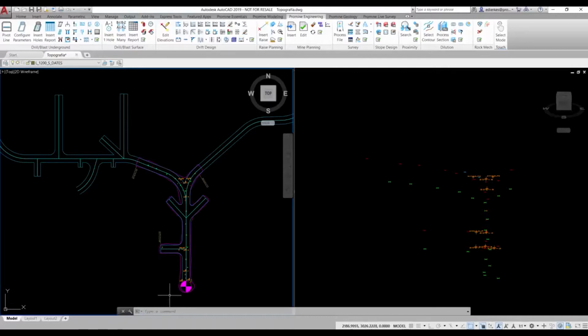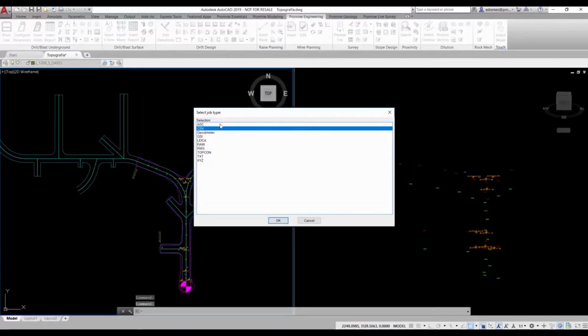information of some segments. As the survey has progressed, we're going to insert additional survey information on the west part of this level by using the Process File command. In the first menu, we can choose between different file types that can be read, like RW5 and TopCon. In this case, we're going to choose the CSV file.